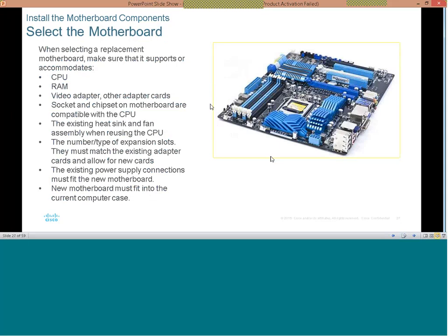So this is a typical picture of a motherboard. This is not far-fetched from what you already know. You can see here, this is the seating of the CPU. So you need to orient the CPU such that it sits properly. You must show your students: before you do that, you press this hook. There's a hook that holds down the CPU. So before you bring out the CPU, you release this hook and take it up. And then when you remove the CPU and probably want to put a new one, you also do the same. While it's up there, you now insert the CPU here.